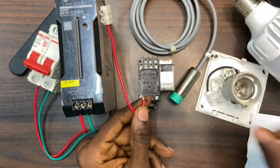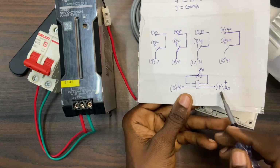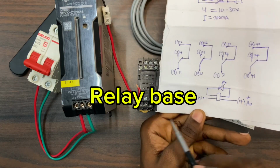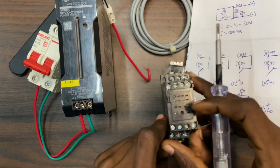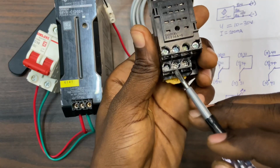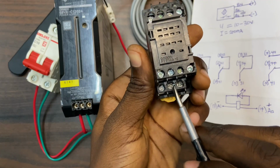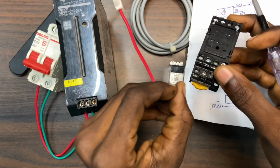This is the positive, and the positive is connected to the, we have 14 and 13, and 14 is the A2, that is the positive. What I will look for on the relay is number 14, and 13 is negative. We have number 14 down here. This is 14. This is number 4. There's an arrow over here pointing to this side. So this is the 14 terminal. Connect the positive.